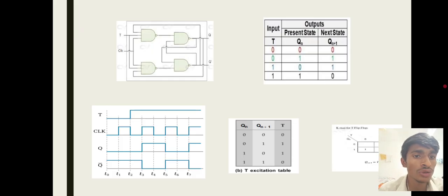It is used to hold data temporarily in computers and digital devices. D flip-flops are typically arranged in groups to form registers that store multiple bits of data synchronously. A shift register consists of cascaded flip-flops that shift data serially, enabling data conversion between serial and parallel forms, useful for data transfer, communication systems, and digital signal processing. Flip-flops serve as fundamental digital memory elements and timing synchronizers, integral to counters, dividers, registers, and various control and storage functions in electronic systems. This is the topic about flip-flops.